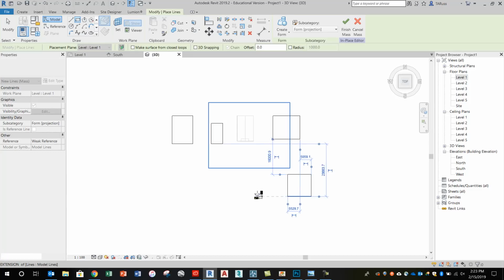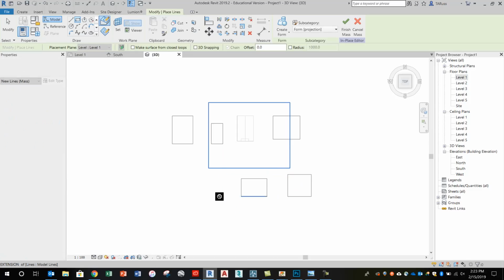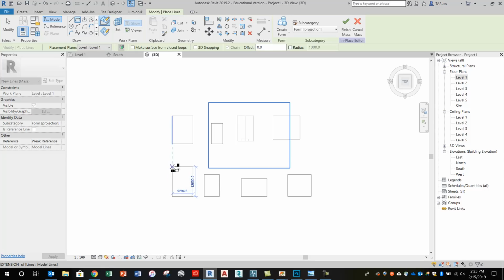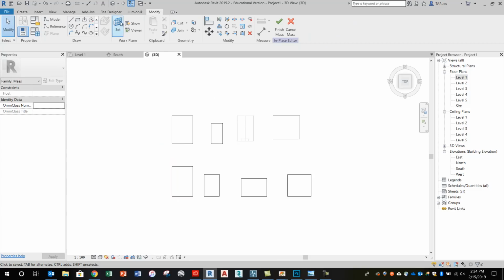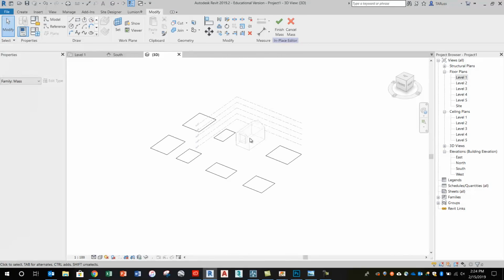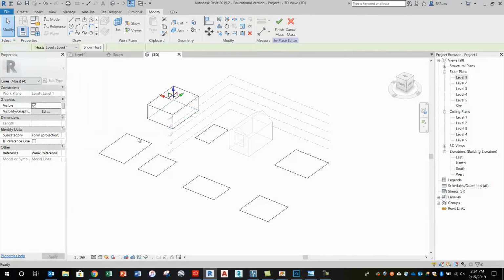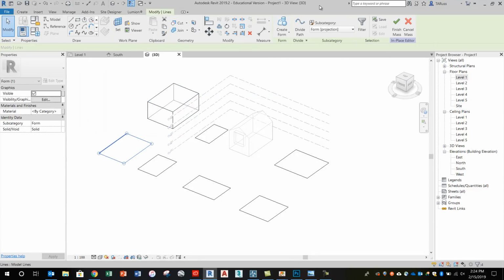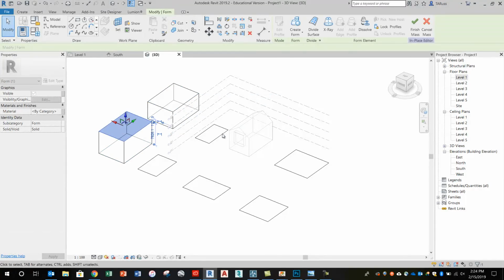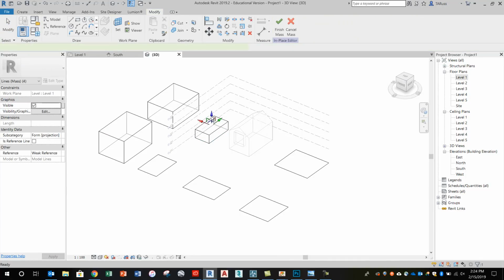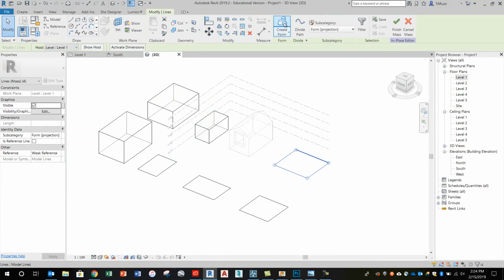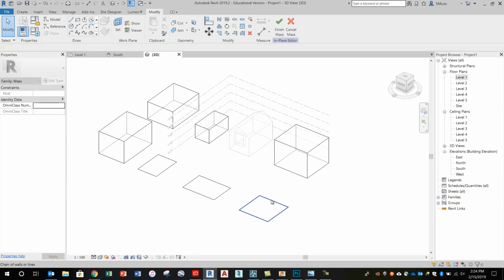And these are important because when I do my solar radiation analysis and then the energy analysis, the shadows that these buildings cast, and maybe the wind that they block for another analysis step that we'll do later, will have an impact on the analysis for the building at the center here. So notice that with all of these, I just did them as one mass block in one mass block session. You have to click on each individual little shape here and extrude them separately, but when I finish, these will all be selectable as one mass object, which is fine because I'm not doing the analysis on them. I just need them there for a little bit of context.